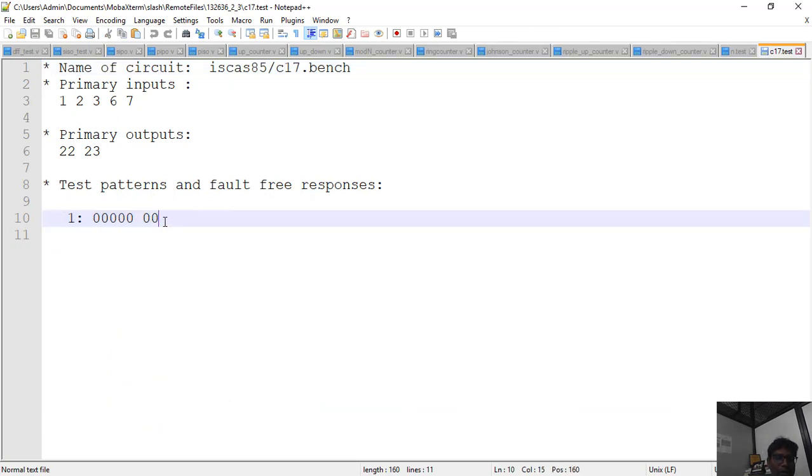You can randomly go and edit this using gedit and give a couple of test patterns. In the initial case for the first command, I think we generated 7 test vectors. If you give all the 7 test vectors, you would have 100% fault coverage. When you remove test vectors one by one, you could see the fault coverage goes down, which means some of the faults get undetected.